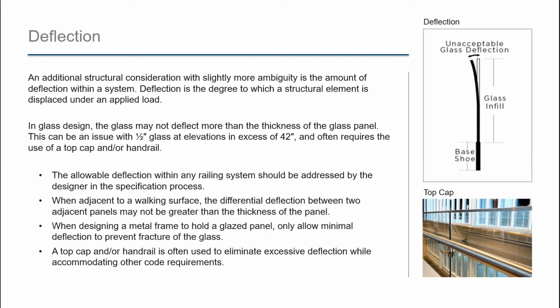To note, there are certain organizations, such as LAWA, the Airport Authority in LA, and DSA in California, the Division of the State Architect. They do have certain deflection limitations, but they are rare amongst jurisdictions. In addition, the feeling of a safe system is very subjective, especially for a system which is in reality rarely loaded to its design limit, or to that 200-pound concentrated load or 50 PLF.